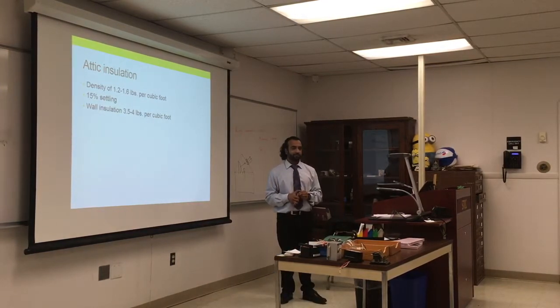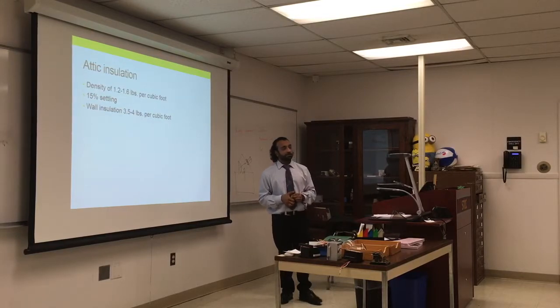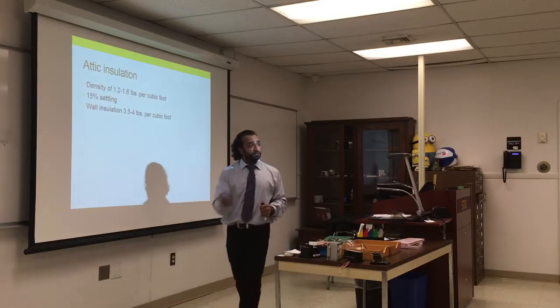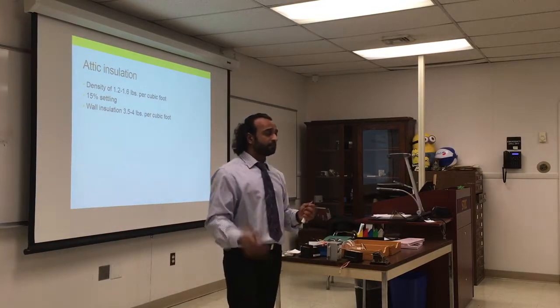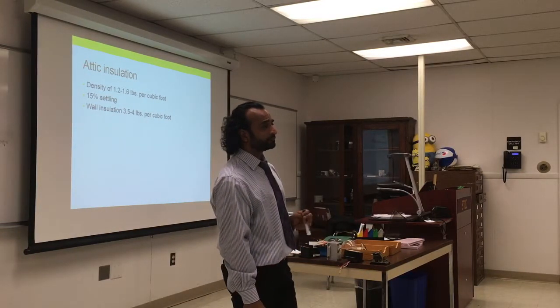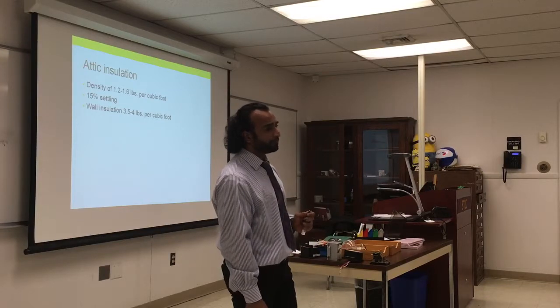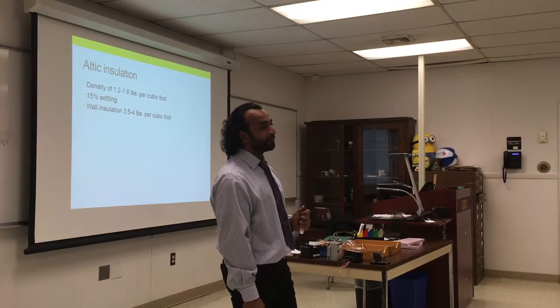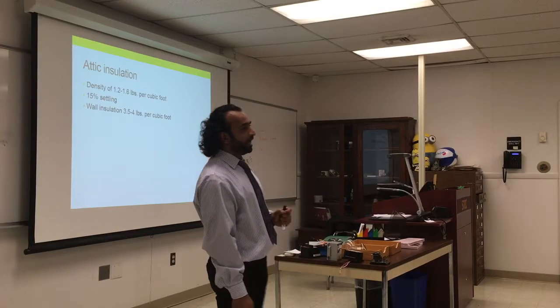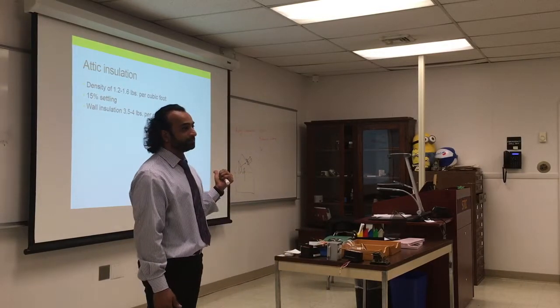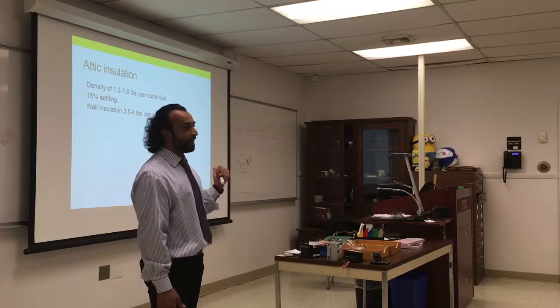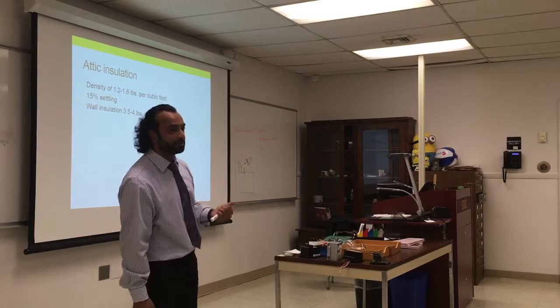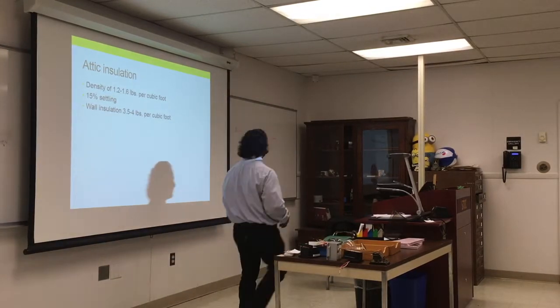You put them in before you put the roof on, or the plywood. It's a piece of foam that goes up against the wood to keep the wood airflowing. Does it vent to the outside? Yeah, air could come in one soffit, go up through each bay and then down through the other side. As long as you vent outside, then you're fine. Don't vent into the solid cavity, because that will again cause ice dams and increase humidity.